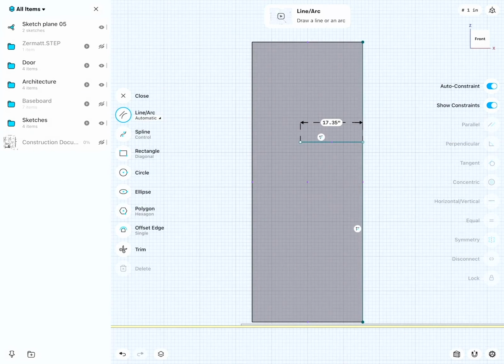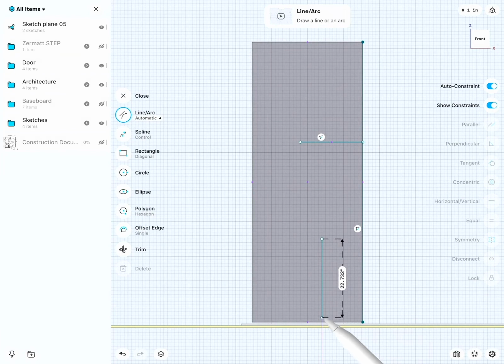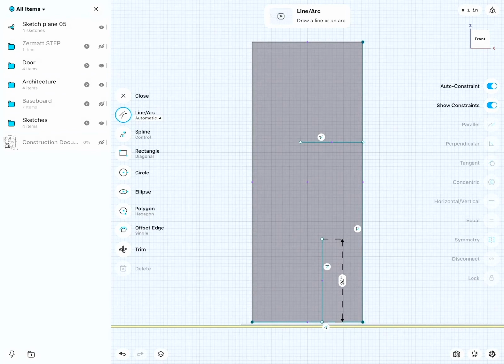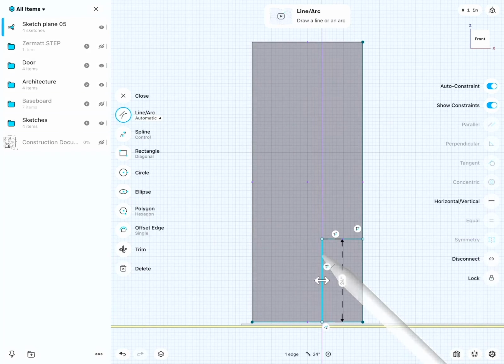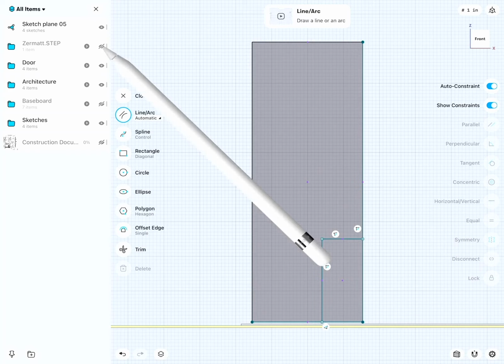And when I do a new sketch on it, I can project in the left and the bottom edge and give each one a dimension. So I could specify this center point. And that's actually what I was looking for.